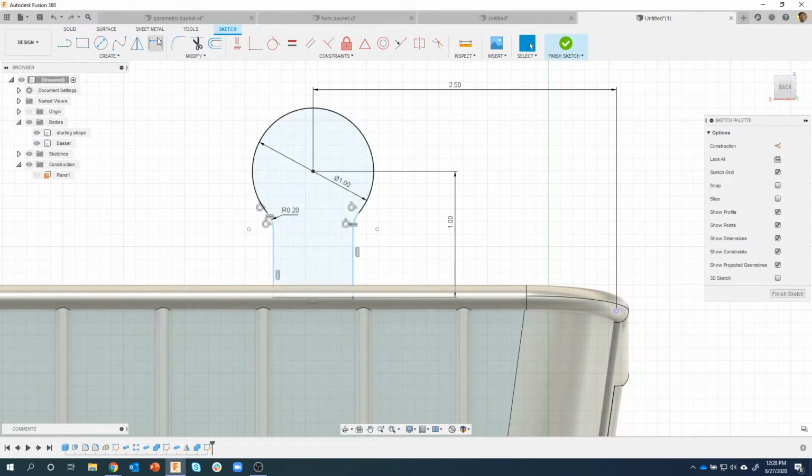So I want to define the width of this rectangle to be 0.4. But again, notice what my sketch did. It's kind of weird, right? So how would I fix this? Well, another cool trick. I want the center of this line, this horizontal line down here, to be perfectly in line with that guy. So I'm actually going to draw a line from the center of that line to that point right there.